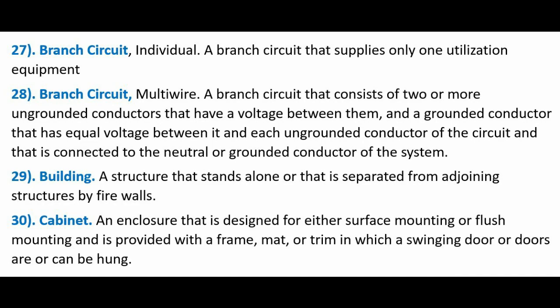28. Branch circuit, multi-wire. A branch circuit that consists of two or more ungrounded conductors that have a voltage between them, and a grounded conductor that has equal voltage between it and each ungrounded conductor of the circuit and that is connected to the neutral or grounded conductor of the system.